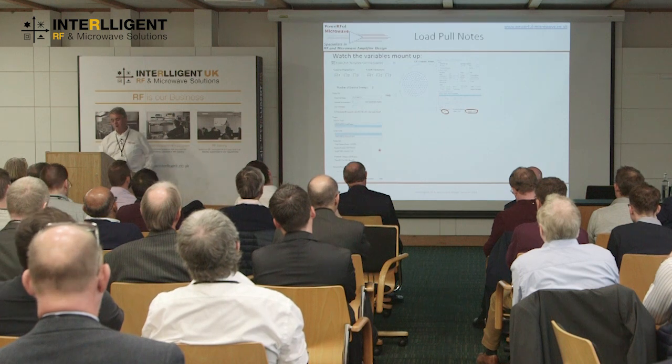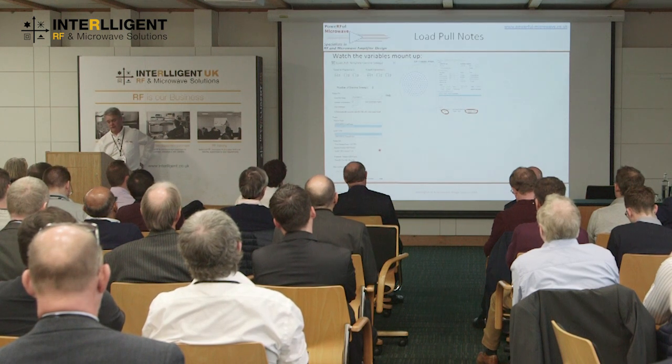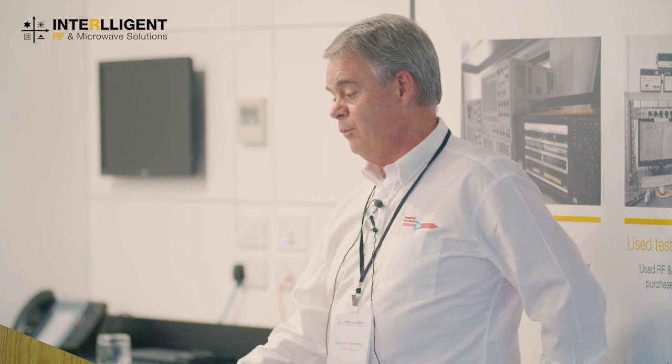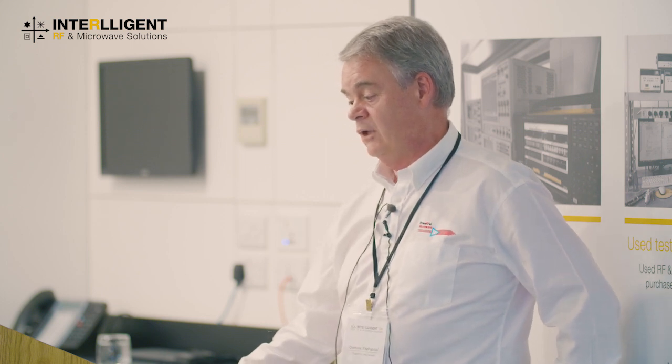Now, a quick point on the number of variables in a load pull simulation set. You've really got to keep an eye out, as the data file can quickly pile up. And it's especially relevant if you want to do any post-processing, as I've mentioned. Particularly at the start of a device evaluation, you might want to keep the data set smaller. For example, if we assume that we've got 6 frequencies, 16 power steps, and we're going to vary over 3 gate voltages, that's already 288 simulations.